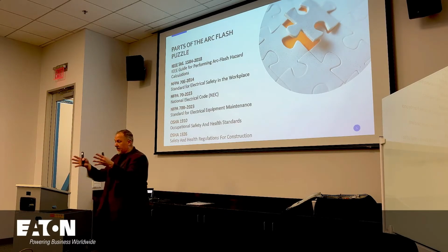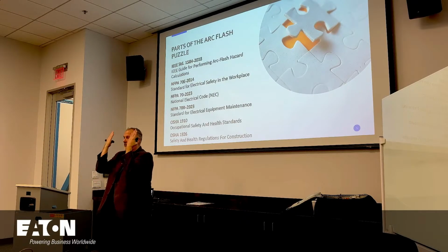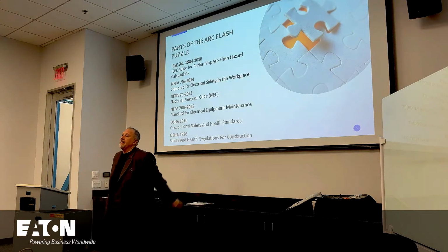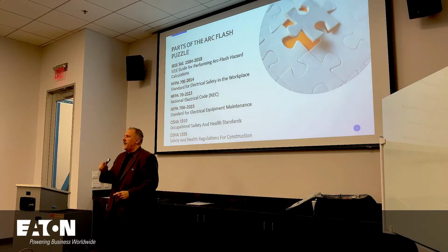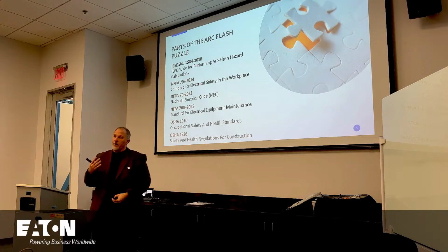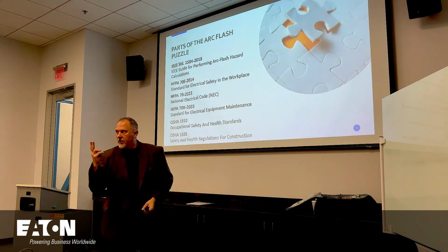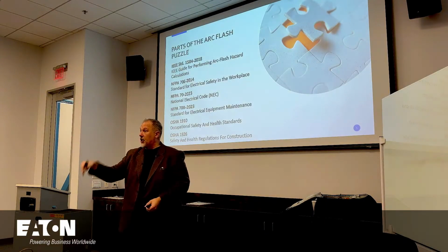Right? So we put all this money in to calculate incident energy, and we made changes to the equations to account for the size of the enclosure. Smaller enclosures push more energy out the front. Larger enclosures don't focus as much energy. Whether the bars are this way or this way makes a difference, and whether they're this close together or this close together makes a difference. There are a lot of parameters in the additional testing done to publish 2018 that gave us more insight. And it changed two critical things: one was the incident energy calculation, but the other is the arcing current itself.